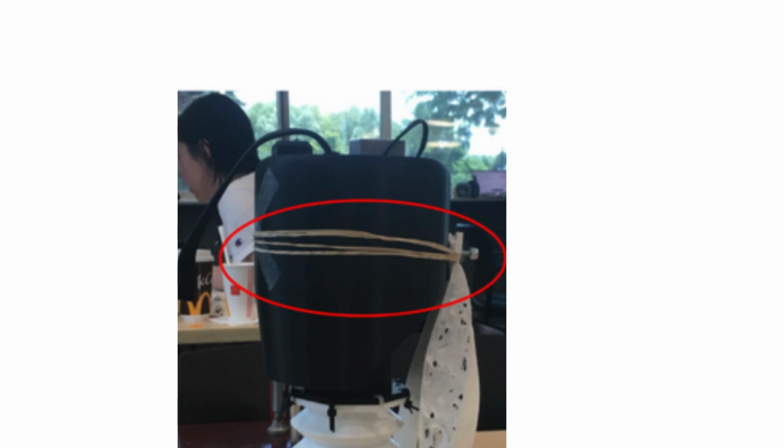Another thing that we noticed was the neck muscles popping out from the securing structures, especially the screws. In our situation, the screws were just too hard to screw in properly, and so we just left it be and tried to rely on friction. However, this would not do the trick. And so we decided to use elastics as well as zip ties to fully secure the muscles onto the head as well as the base. And so this helped improve the head and neck stability, as well as improve the responsiveness of the neck to the collision. So now let's look at our test.